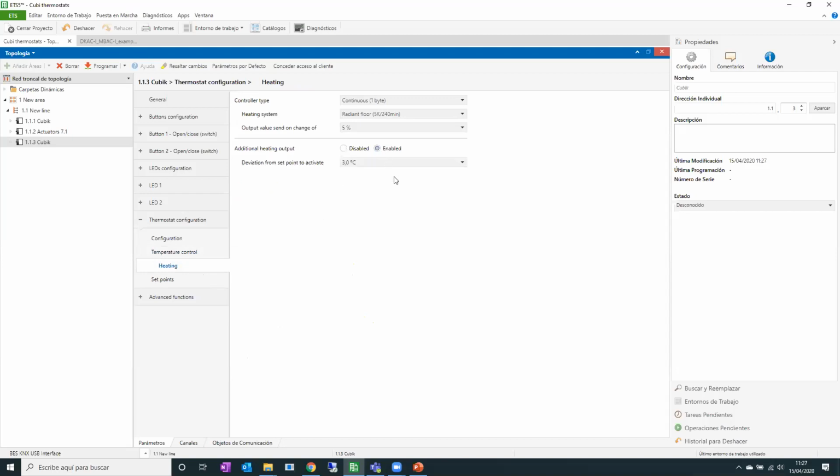But in practice, I use a workaround. I am using the first stage of the thermostat, of the room temperature controller inside the TL, and I connect via a unique group address with the valve actuators for underfloor, but as well with the fan coil. The trick here is that we expect the fan coil to start working when the heating request is bigger than, let's say, 50 or 60%.